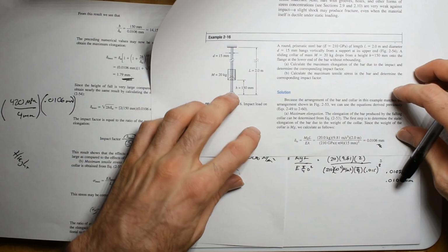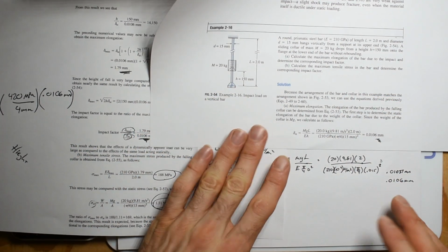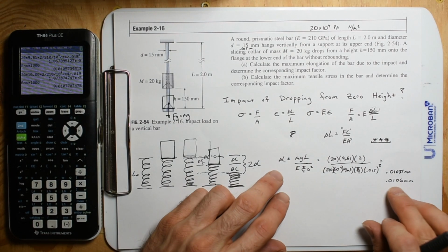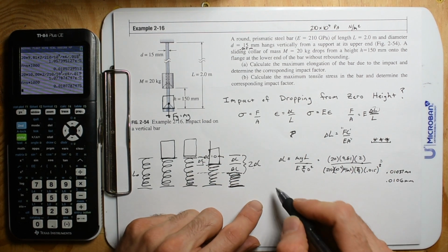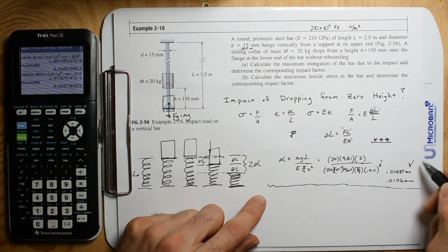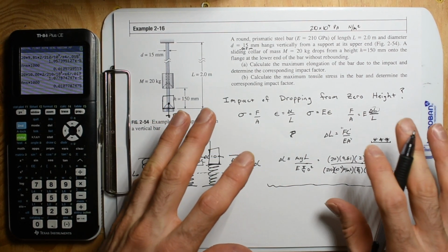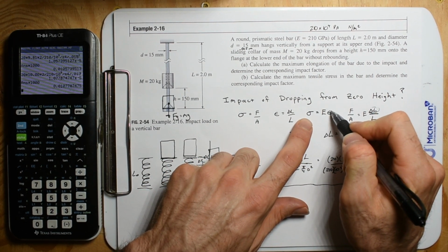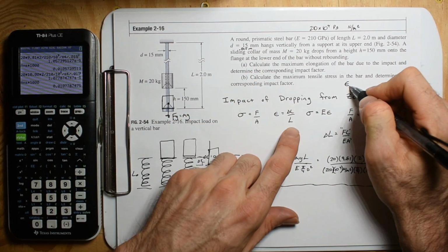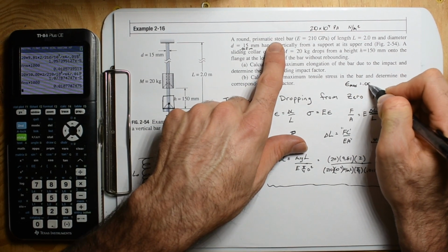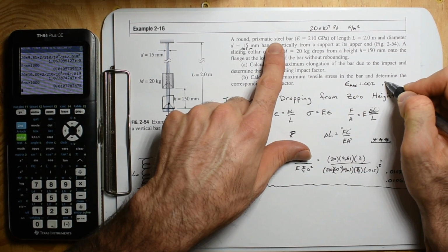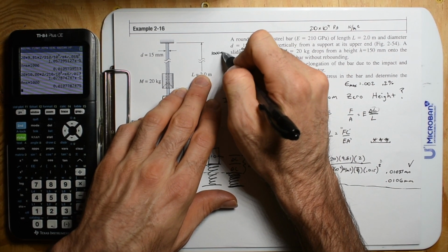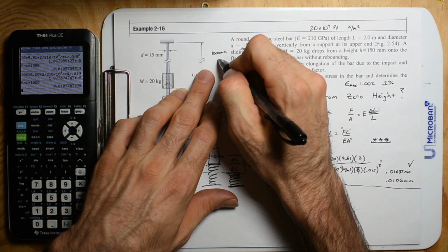Sometimes you love sample problems because you need that check on reality. Because if you've not done problems like this, you don't have any way to double check what the reality is. But we do. So let's go over that, because you're just like, well, how could you double check that this number is 100% accurate? What's another way to do this? We go back to the fact that you just have to know this. It's not even in the problem statement, but the max strain for steel is 0.002. You can stretch it 0.2% of any given length. If you have 1 meter, that's 1,000 millimeters, and you stretch it 0.2%, that's going to be 2 millimeters.